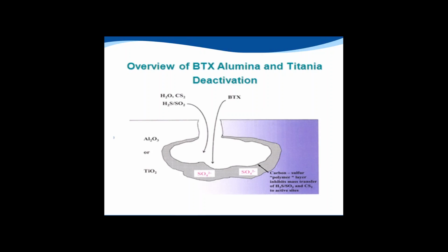Over time, this process was hard to control, which led to what we have now, the conventional way to recover sulfur at gas plants and oil refineries by way of the modified Claus process, where we have an intermediate step at the reaction furnace where we produce SO2, such that downstream we can react H2S and SO2 to produce sulfur vapor, which is a more moderately exothermic reaction.